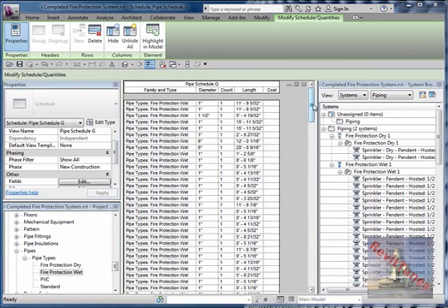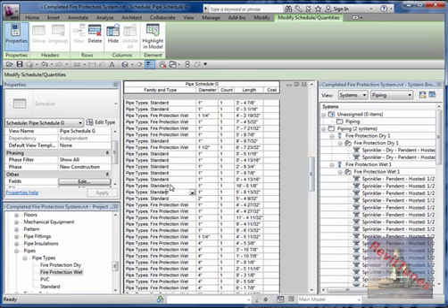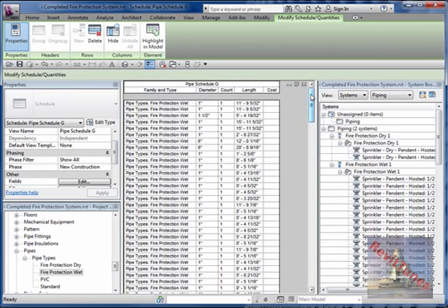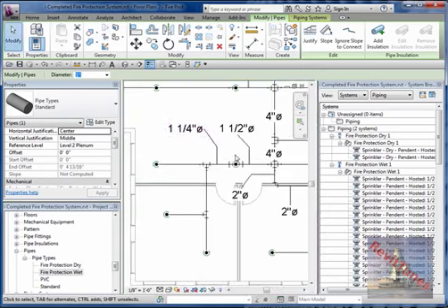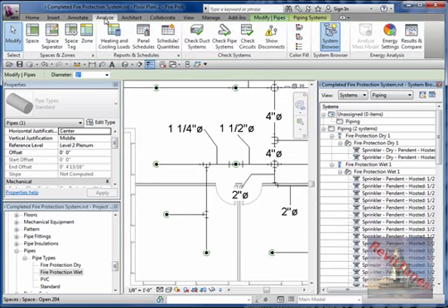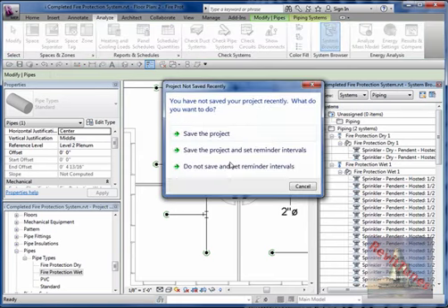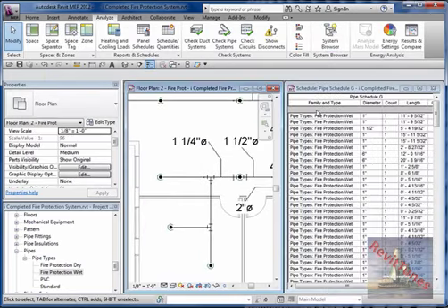Okay, so now by looking at the chart right here, the schedule, if you see every pipe right here, it says wet system. Some don't say if it's wet or dry system, and none of these pipes says dry system, and this is a good tool to verify if I have a mistake in my layout here. So I'm going to hide for now the system browser. So it's in Analyze, hide the system browser, don't save, and I'm going to put side to side this.